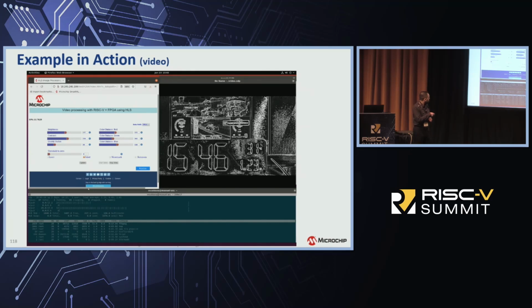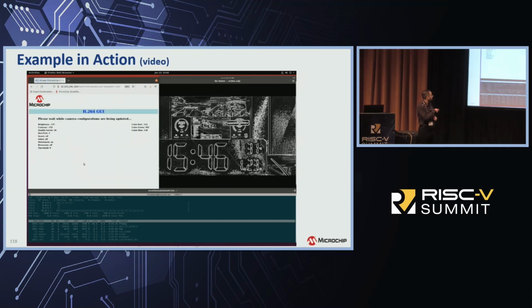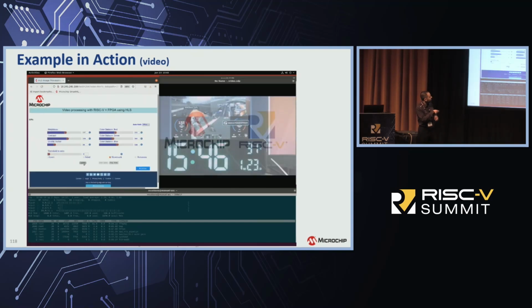There is a little bit of usage here for the CPU, but that's not because of Sobel. That's more related to the networking stack, and I'll show you at the end where that increase in usage comes from. This is the watermark that I told you about. So the RISC-V processor loads that image, and then the hardware accelerator brings it in and performs alpha blending on top of the video frames, and it's the same frames per second, the CPU pretty much not doing anything.